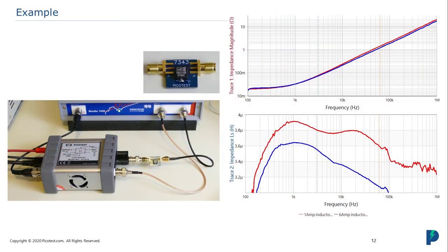And so here's an example using this 3-port FRA method, and you can see the line injector is connected. The isolated current monitor goes to channel 1 of the frequency response analyzer. The modulator output is connected directly across one port of the inductor through the SMA connector, and the other SMA connector connects to channel 2 to measure the voltage across the inductor. Because of the ground loop, remember, we'd really like to have a differential amplifier there, or an isolating amplifier, maybe something like our J2113 or J2102, if you want to get the best quality data.